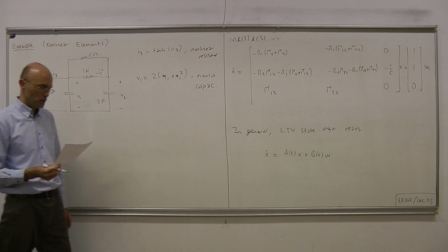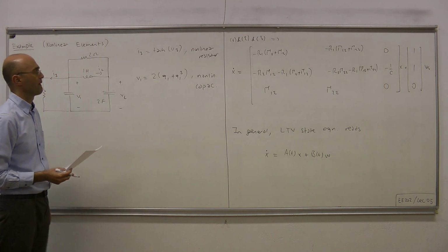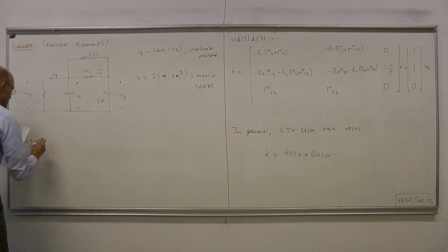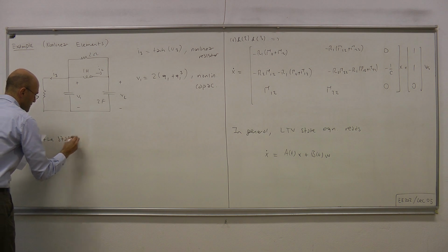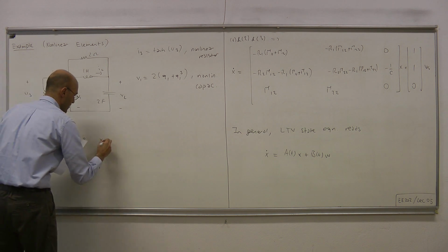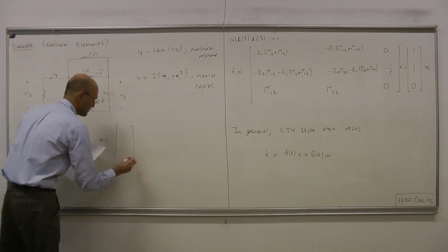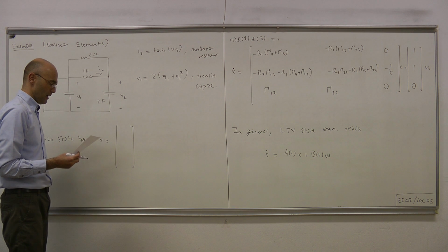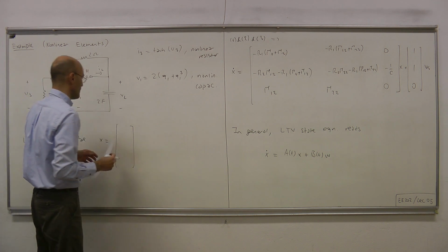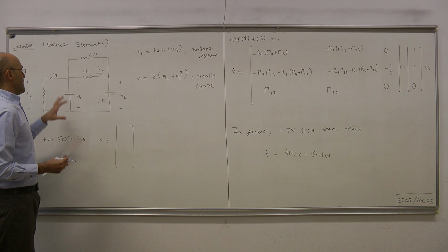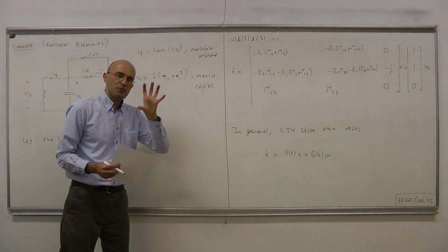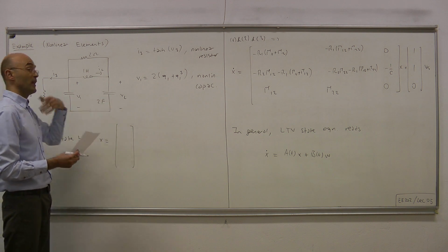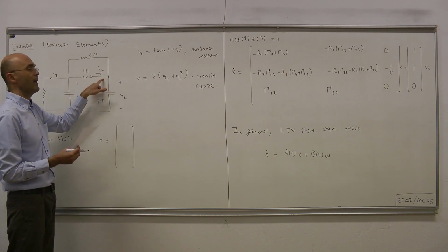Now for this circuit, let's obtain the state equation formulation. Suppose that we perform that proper tree selection and so on, and in the end we figure out that all the capacitors and all the inductors must be represented directly in the state. So regularly, for an LTI circuit, we pick V1, V2 and IL as our state variables.